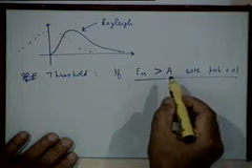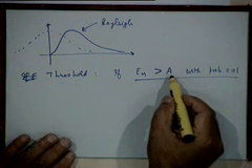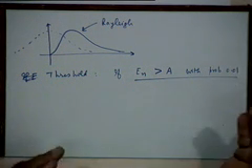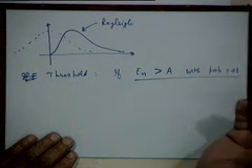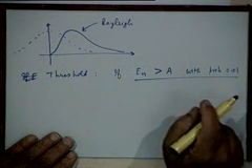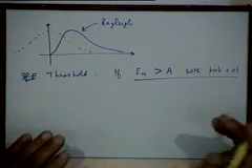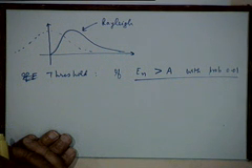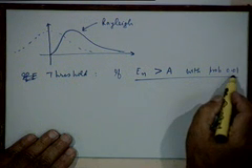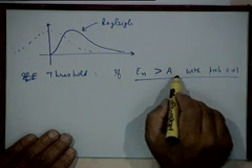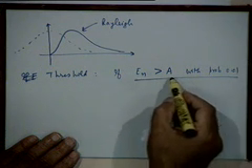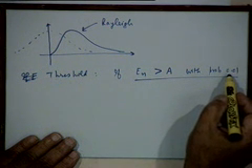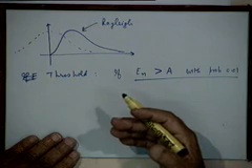Basically, if the probability of noise amplitude being greater than the carrier amplitude is 0.01 or more, then you are in the threshold region, right. So, what is the corresponding signal to noise ratio which will result in this kind of situation? That is what we need to calculate.